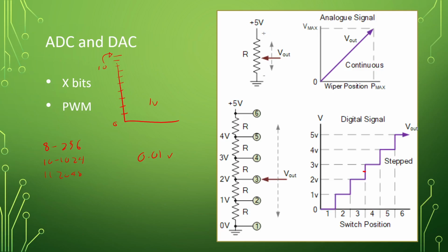All right. We also have PWM. Anyone know what PWM stands for? That would be pulse width modulation. All right. So oftentimes when we are dealing with analog signals from a digital world, we're not actually sending true analog values out. All right. What we're doing is we're pulsing an output to make it look like it's that analog signal.